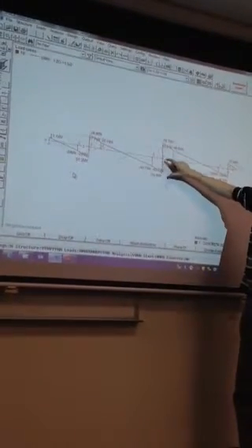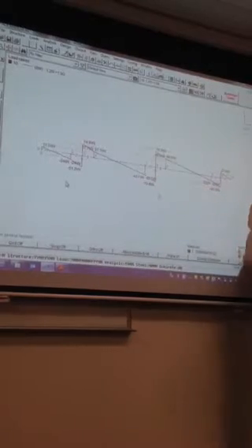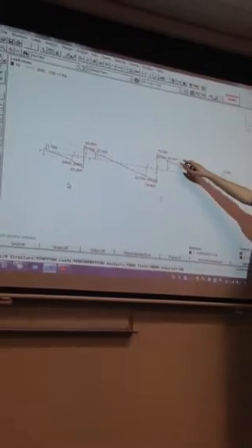So the way that I was getting those bending moments, there's a little bending moment diagram here. You can turn that off. You can put the shear force on. So we'd only be designing our shear force at this interface here. We wouldn't worry about the maximum, because the maximums, again, we've got the bigger effective depth. So we'd only be designing our shear force in the slab for that 43.7. In fact, that one's slightly more, go to 49.5. So we're only designing that slab for shear once.